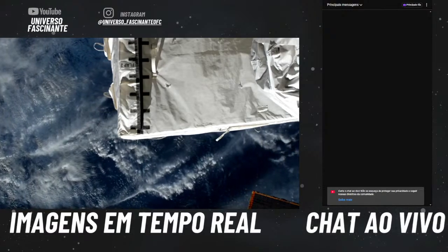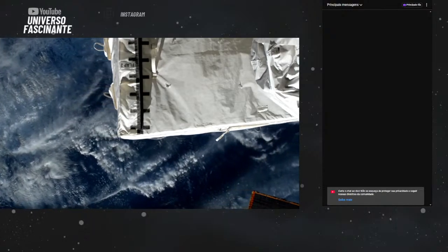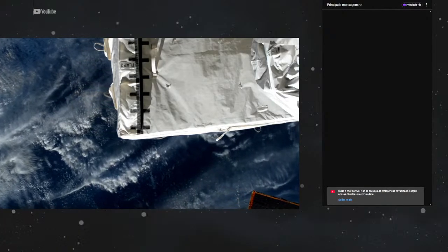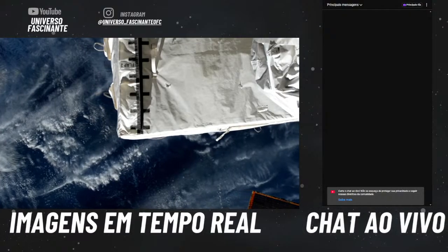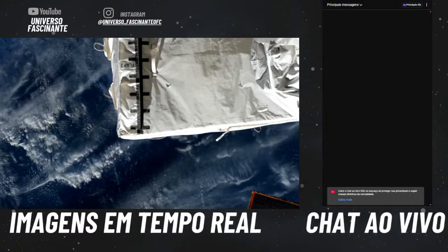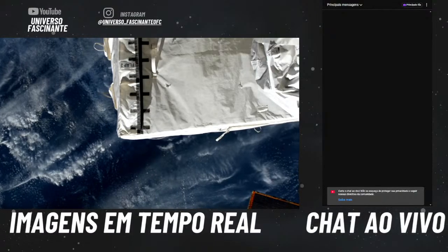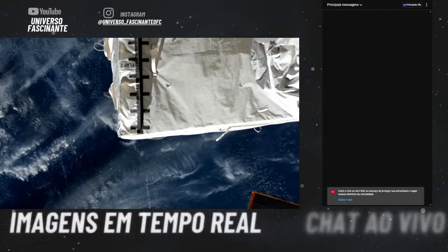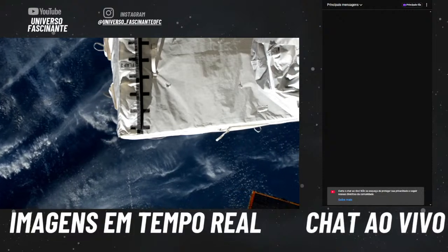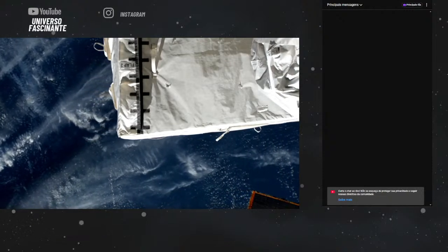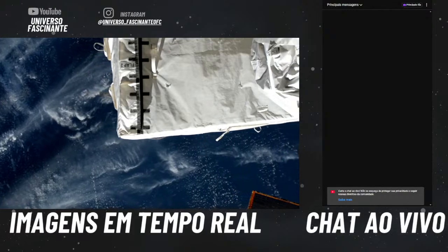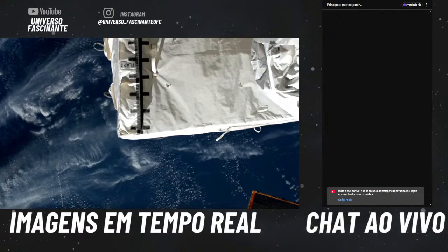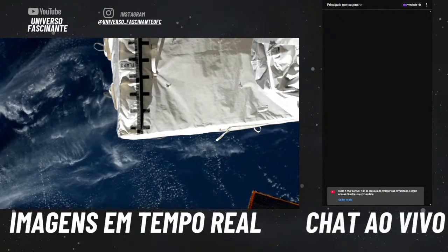As we just saw, the whole entry process begins with the undocking of the Soyuz. Of course, that occurred a short time ago at 7:41 and 30 seconds p.m. Central Time. The Soyuz backs away to a distance of about 41 kilometers away from the International Space Station for the deorbit burn, which is a 4-minute, 42-second retrograde braking maneuver to slow the Soyuz down and allow it to